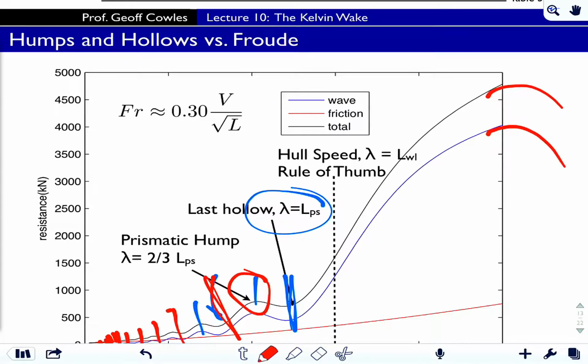Now, what this data doesn't show is that theoretically, the drag does return down here once the wavelength along the hull equals 1. You have 1 wavelength. Now you extend it, and the drag's going to rise and rise until your wavelength is twice LPS, and then it actually starts to drop again. But fundamentally what happens to ships is that nobody powers through to get to that theoretical portion of the curve.